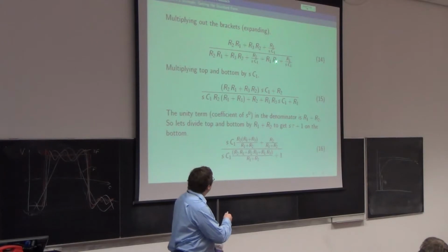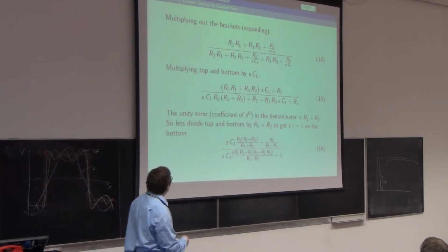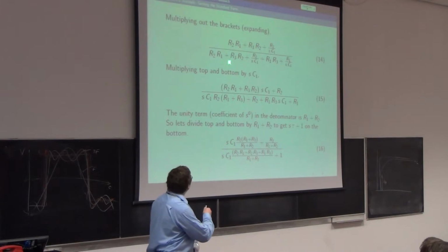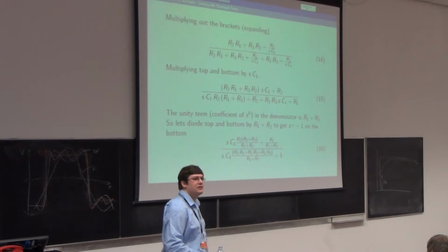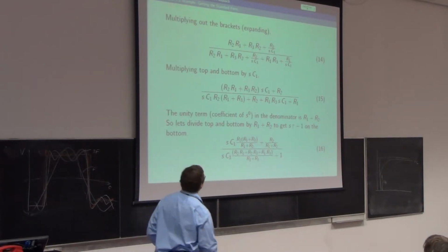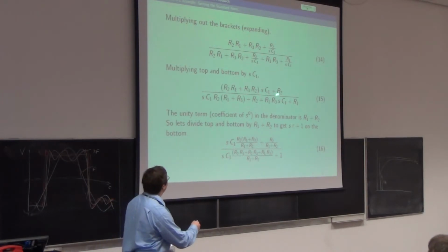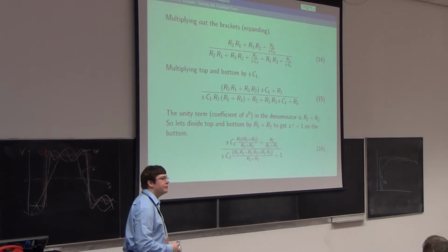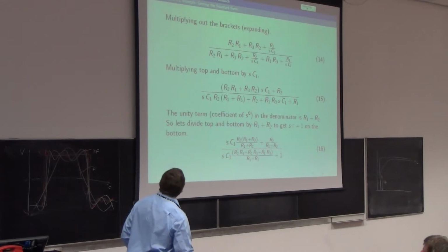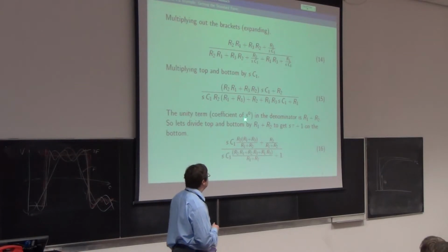Then I have R1 times R3 plus SC1, which is that bit there, and that R1 loses SC1 because they cancel. And on top, I factorise the same as I did. Oh, I factorise slightly differently actually. Oh, I could have factorised out the R2. What an ass. Never mind, you can factorise that if you like. So I've got R1 plus R1 times R2 plus R3 times R2 times SC1 plus the R2, which that SC1 cancels with the SC1 that goes on top. Happy? Good.